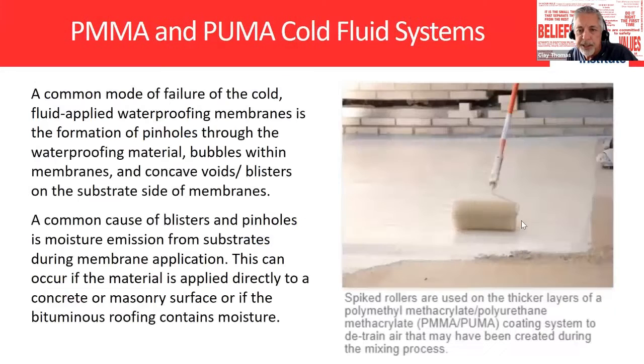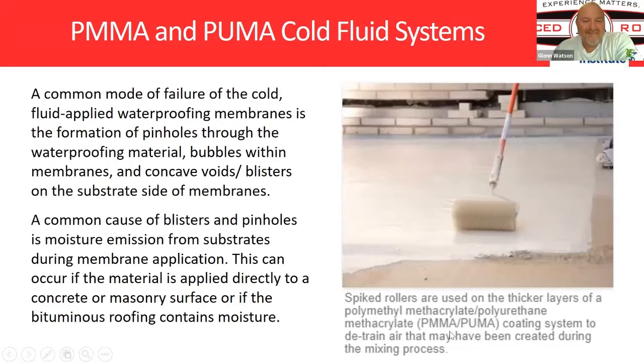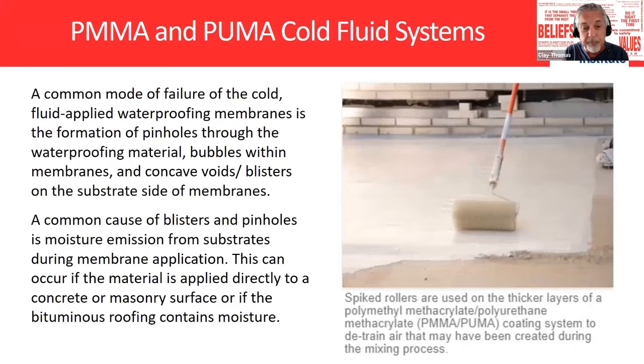One of the things I noticed when you're putting down a PMMA system is this spiked roller. I had never seen it before. Glenn, have you seen them before? Yeah, I have. What that does is remove the bubbles and detrain the air, because you'll hear me say when I talk about mixing, don't lift the bit. You'll entrain air bubbles into the mixture when you do that. So this is de-entraining it.